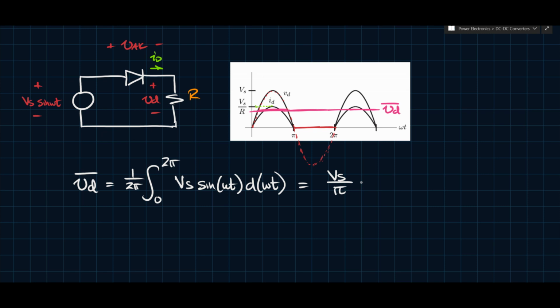So the function of the rectifier is to produce an output with a low ripple content, right? You obviously want low ripples, because the larger the ripples you have, so if this goes between Vs and 0, this is going to introduce some type of noise into your system, which is never a good thing. And so what you want to do is use low-pass filtering between the rectifier output and the load. So if we were to think about it here, we can say that this is the output of the rectifier and then the resistor is the load, right?